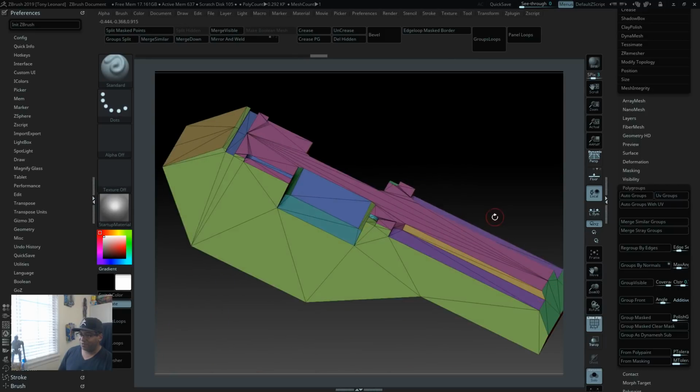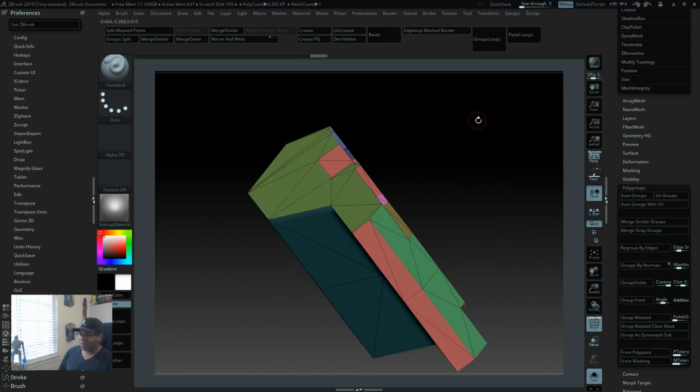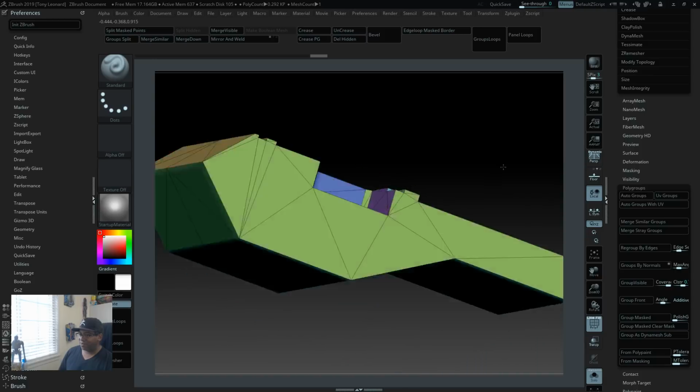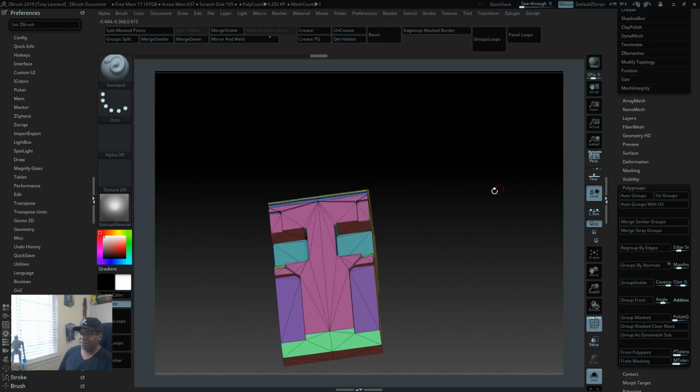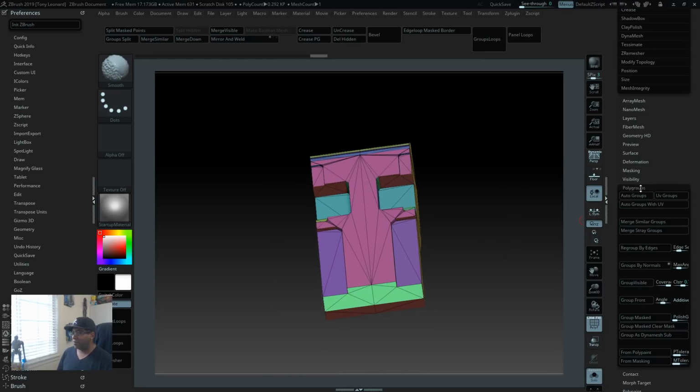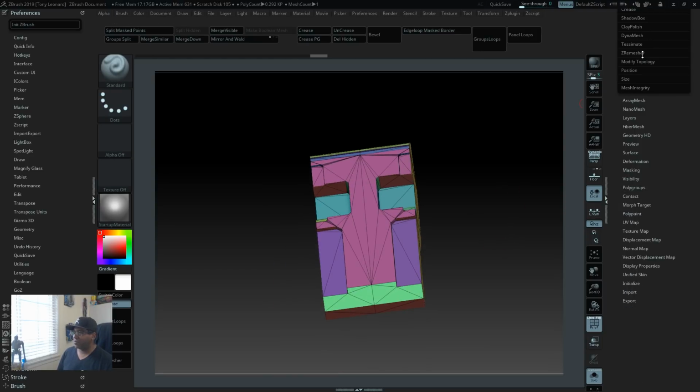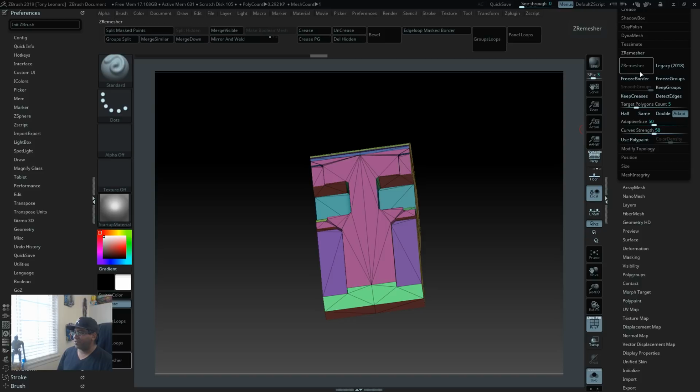That's a little bit more definitive. Okay, so let's just try it there, because I think every flat area is pretty much different. No need to make them the same. I think that's probably good. And now, let's try a few things with ZRemesher. So with ZRemesher, I'm going to turn on Detect Edges. And I'm going to keep this fairly low, maybe 8 for starters, which I guess would be 8,000 for the polygon count.